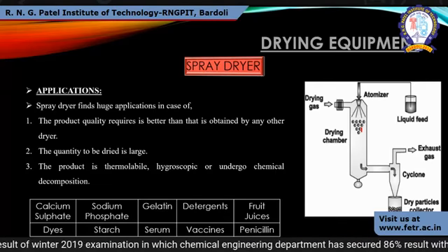So this is continuously in one rotation. It is operated at 1 to 10 RPM, right? The conduction mode of working is very simple. Heat is transferred by conduction and it will evaporate the moisture from the outside surface. So this outside wet solid is dried and collected in the screw conveyor.